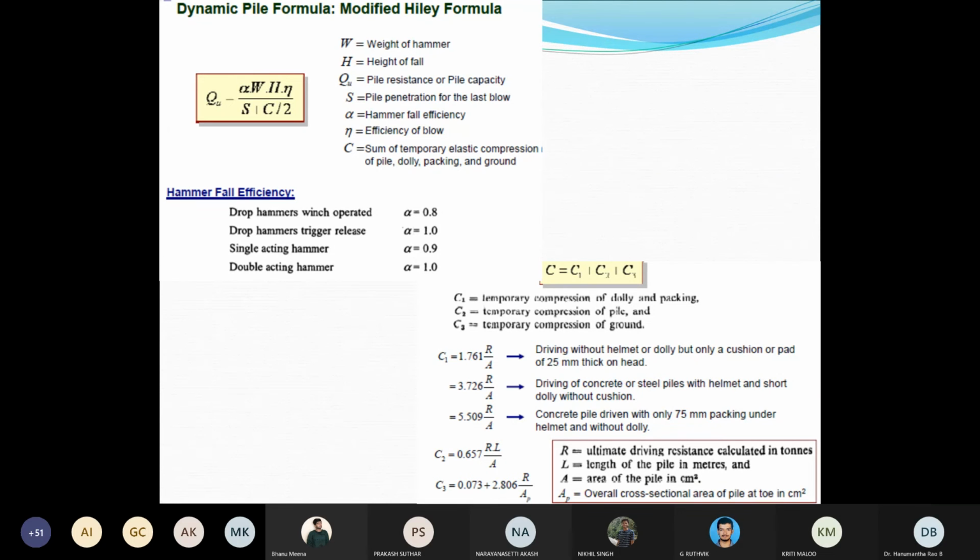Suppose the rammer directly contacts the pile top, if the impact is directly on the concrete, no doubt the top of the pile gets cracked. That means the direct impact of the rammer on concrete is strictly avoided. So this is common sense.